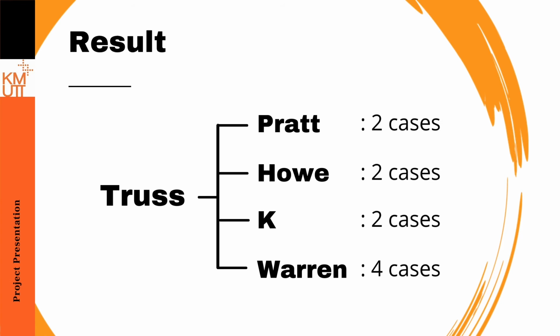The trusses are designed with different numbers of panels depending on the geometry of each pattern. All cases are designed with the same condition that the truss occupies a full story height, 4 meters. The standard for controlling efficiency of each section is the demand to capacity ratio, which should be as close to 1 as possible. Due to the long span and huge load, the built-up hollow square section is considered with dimensions from 200 to 800 mm by increments of 25 mm.